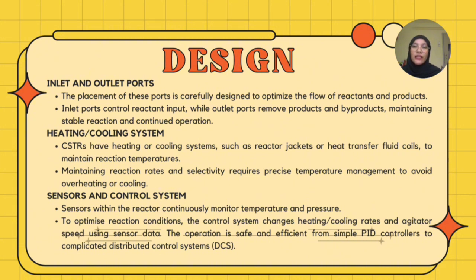And the last one, sensors and control system. Sensors continuously monitor temperature and pressure, and the control system adjusts heating, cooling rates, and agitator speed to maintain optimal condition. This can range from simple PID controls to advanced distributed control system.